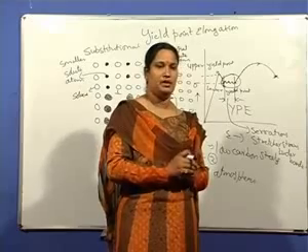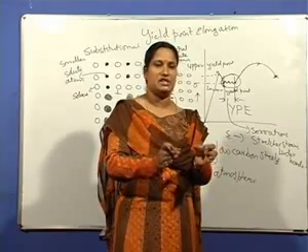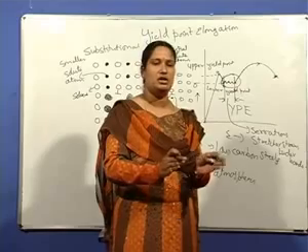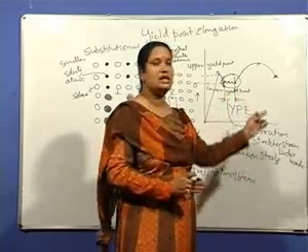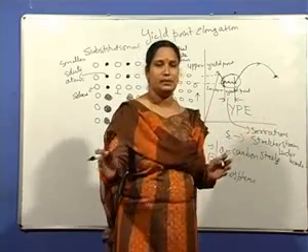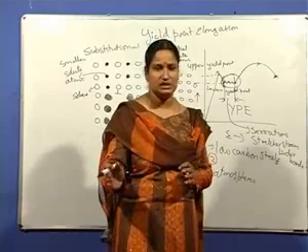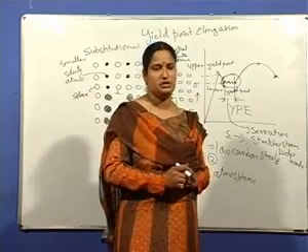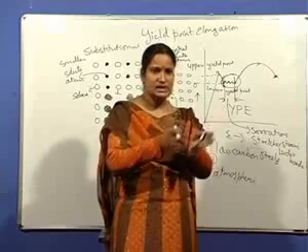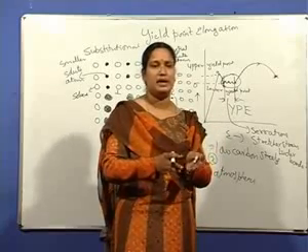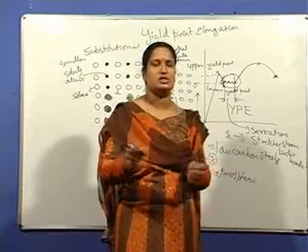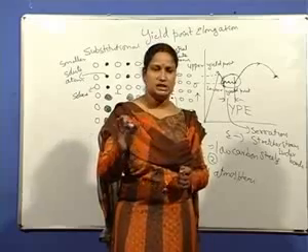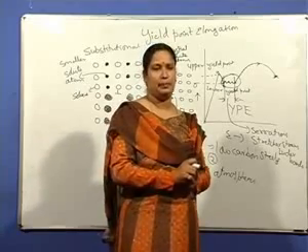During forming, one portion of the material has undergone plastic deformation, which gives rise to this yield point elongation, while the other portion has not yet received plastic deformation. So these structure strains or Luder bands are seen as a rough appearance on the surface of the sheet materials during forming operations.